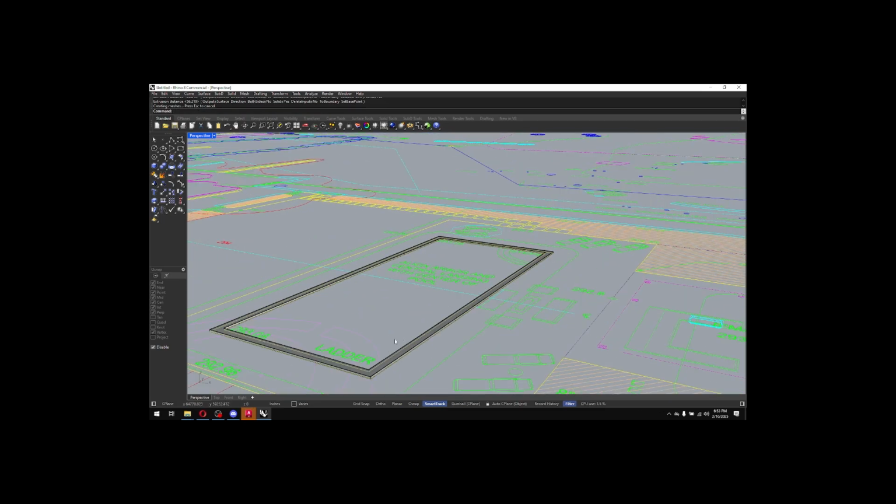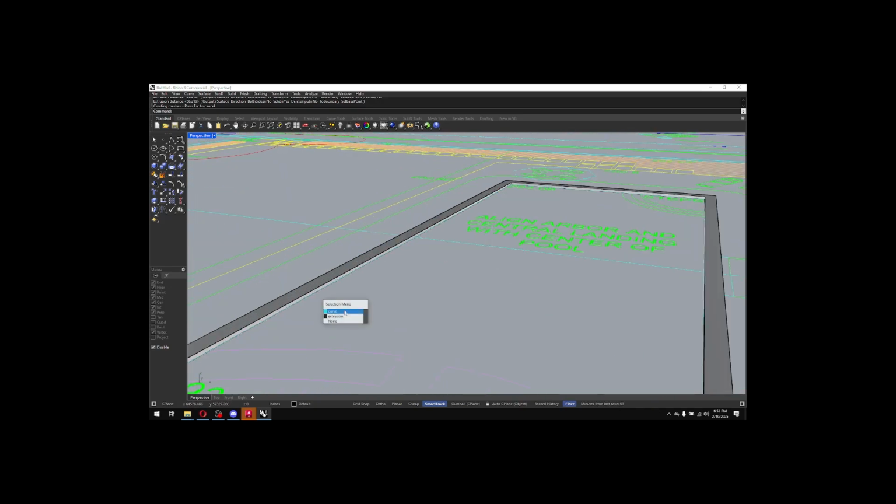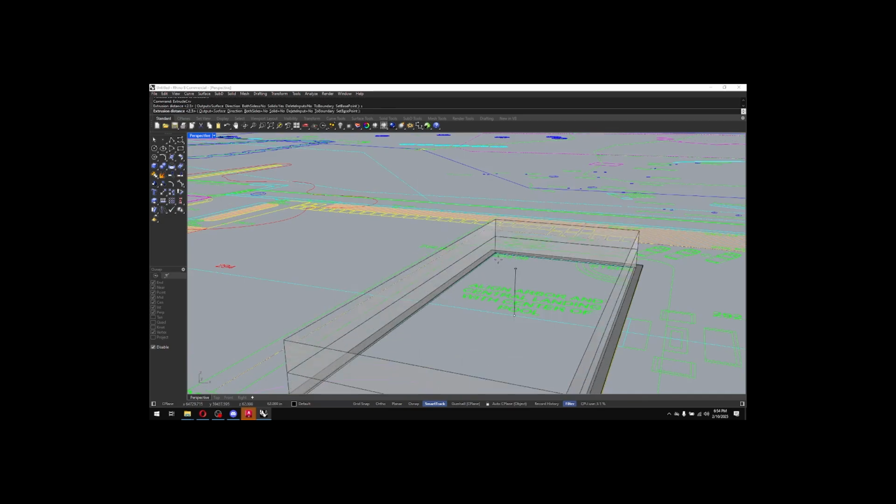Then if I want to continue creating this pool, let's say this is the elevation we're at, but now I want to build the inside of the pool. Well, I'd select that inside edge of the coping, and offset, just like Rhino. Coping usually hangs over about 2 inches, so I'll do 2. Select that line. Extrude curve. Let's say we want solid off.